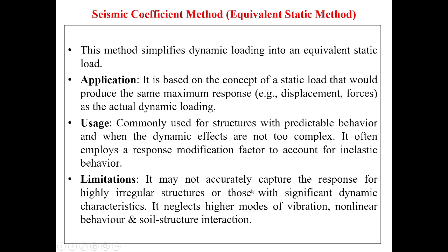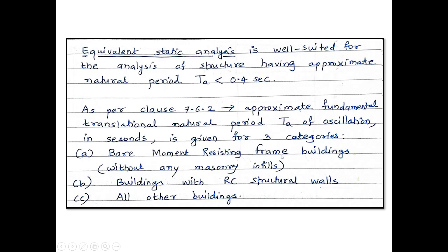However, there are certain shortcomings or limitations of this equivalent static method. It may not accurately capture the response for highly irregular structures or structures with significant dynamic characteristics. Again, it neglects higher modes of vibration and also it neglects non-linear behavior and soil structure interaction. So let me go further.